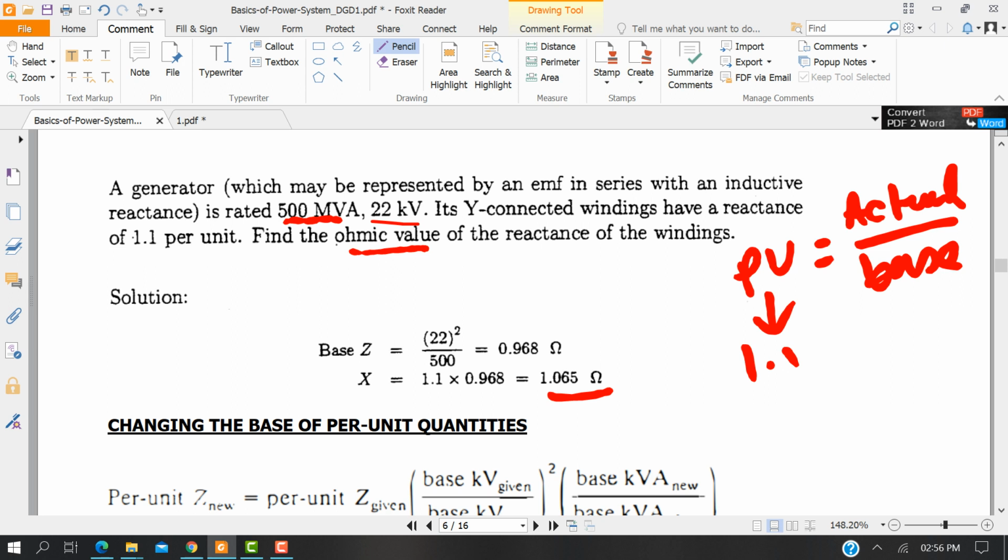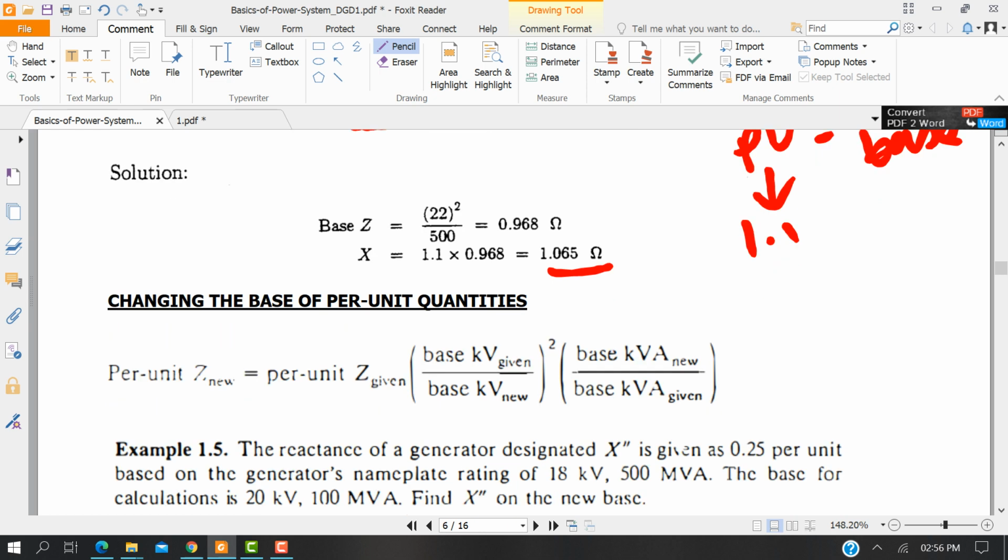So to express all the components in the same unit, we use the per unit expression. It's just like a normalized value. We have to consider a reference base value, and if we divide the actual value by it, we get a lower value, whereas the base value would be higher. If there are two or three more components, the expression can be written accordingly.